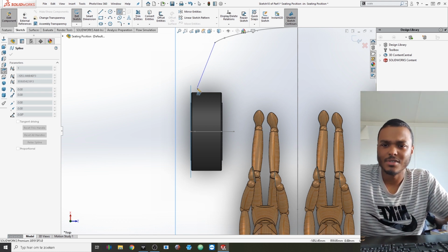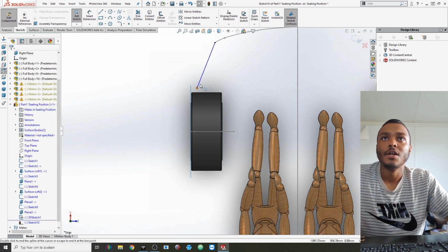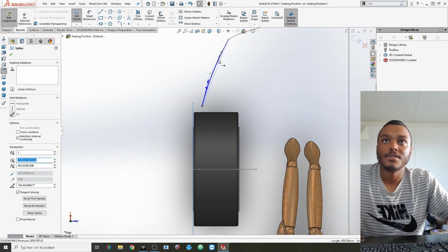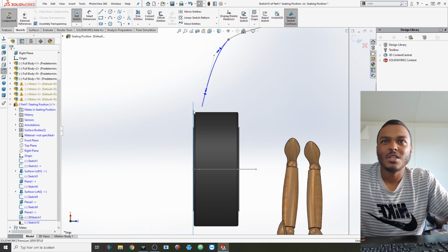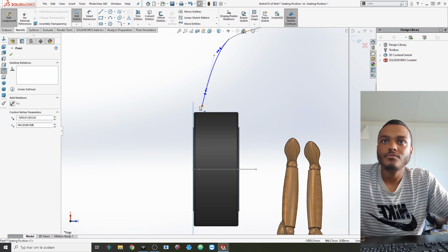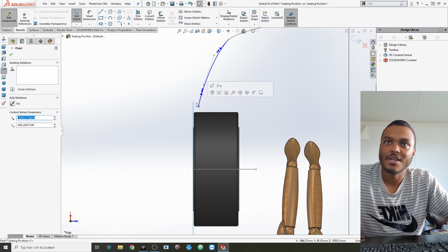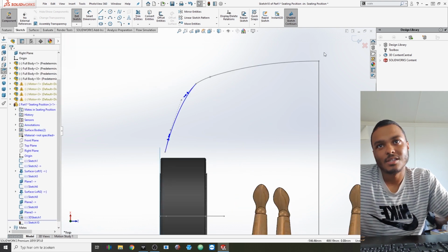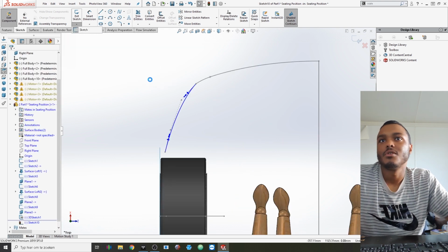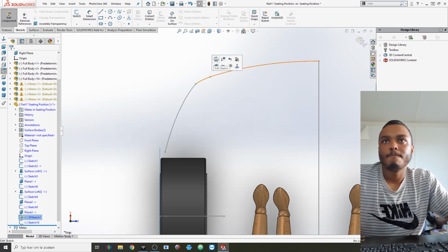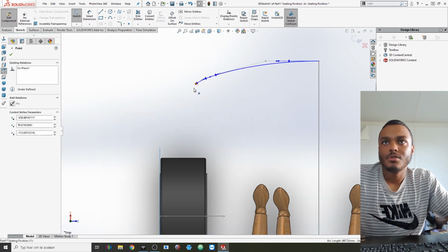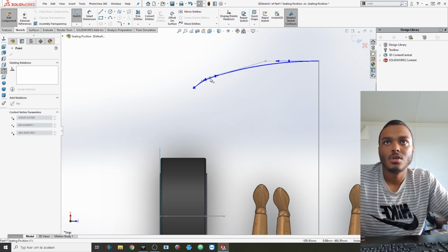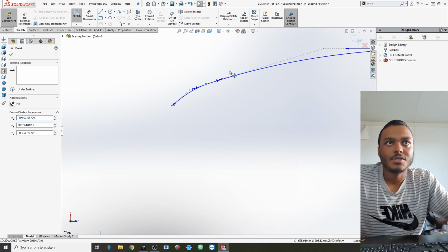So those are all design tricks that you can use to make the underside of the car appear smaller and closer to the ground than the rest of the top surface. So make it a little bit wider, but we want to see a little bit of the tire on the front when we look at it. So I think that would be good, but I'm going to make this line curvature a little bit more rounded off. So drag this point a little bit closer to here, drag this point a little bit closer, and then round all of these edges off.